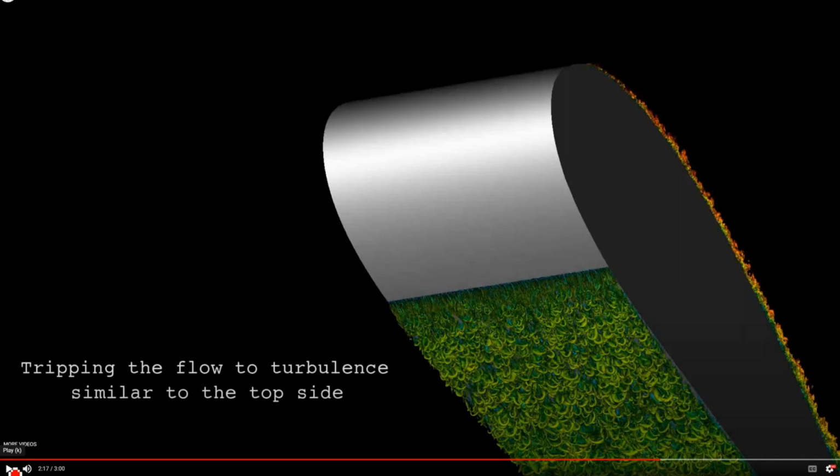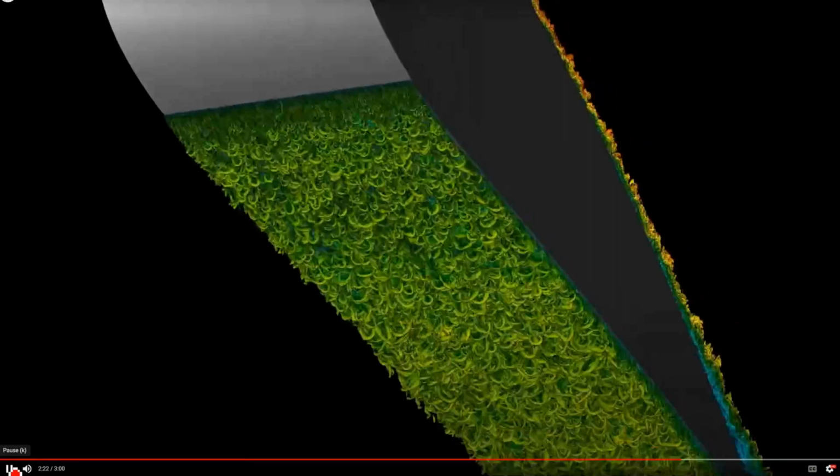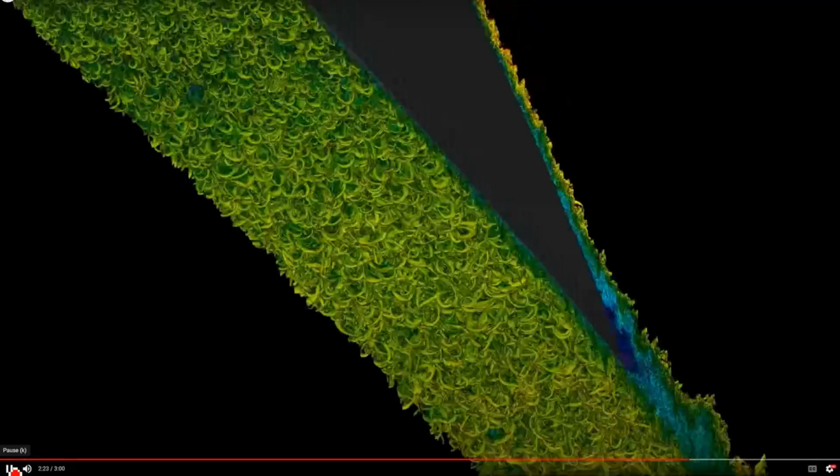Actually, what we simulated in aerodynamics with the k-omega or k-epsilon model does not exist in real life. This is what exists in real life. This is what we could see on a real airfoil. But with the k-omega and k-epsilon averaged models, we can also track an important thing: the behavior of skin friction on the surface.